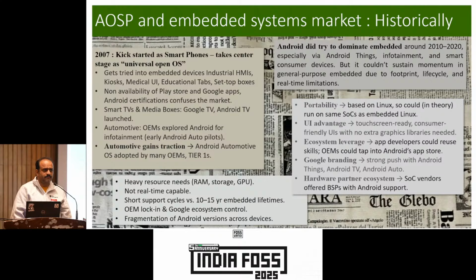It is a bare metal dual core Cortex A53. It is TI's latest generation AM6 series, the AM62 series of devices, AM62L we call it. So it is a very light microprocessor just running bare metal Linux.